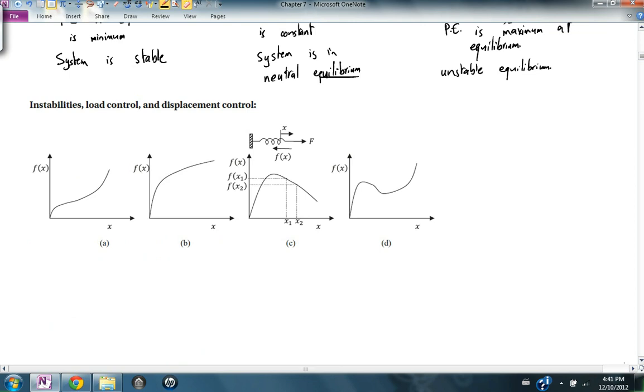So let's look at our curves again and try to understand what stability and instability mean when it comes to springs. As we said, these two nonlinear springs are stable. Any descending curve for a linear or a nonlinear spring corresponds to an instability in the system, and the instability can be seen as follows.